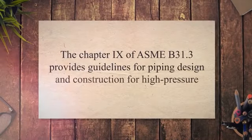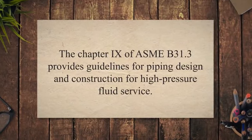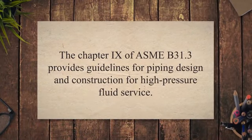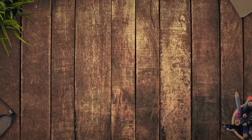High pressure fluid service refers to service exceeding the ASME B16.5 Class 2500 pressure temperature rating for a material group. Chapter 9 of ASME B31.3 provides guidelines for piping design and construction for high-pressure fluid service.